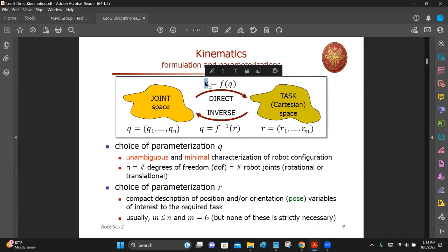Using whatever format you want to define the orientation in. Maybe you can get the roll, pitch, yaw, three angles, or anything else for that matter, right? So all that connected together, assembled together, is R. That is the description of the position and orientation in Cartesian space. All right, so this is somewhat easy. This problem, forward kinematics, is easy, whereas inverse kinematics is not easy. It's difficult to solve. I think earlier we looked at that problem, right?